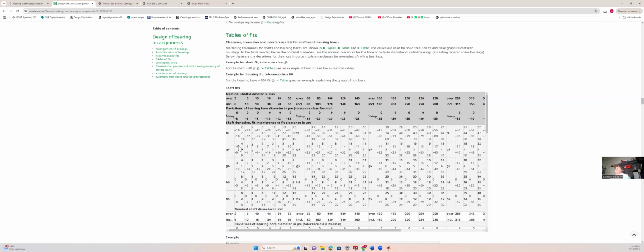So what I want you to do: I'll have a bunch of bearings that I buy, and each one will be slightly different. They'll fall within this tolerance categorization. You need to find a shaft and bearing combination, and you'll use calipers or micrometers to measure this, so that you fall between 1 micron of clearance and 12 microns of clearance. Sorry, I might have called it thou before.